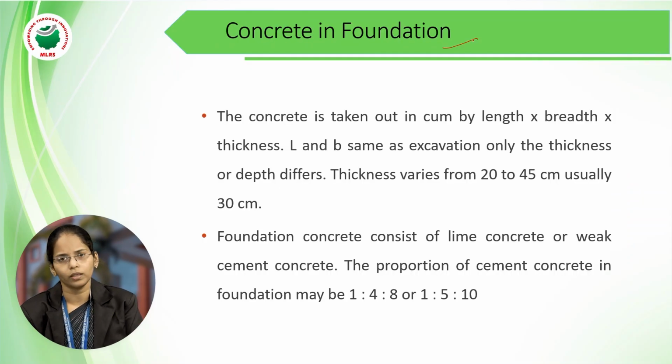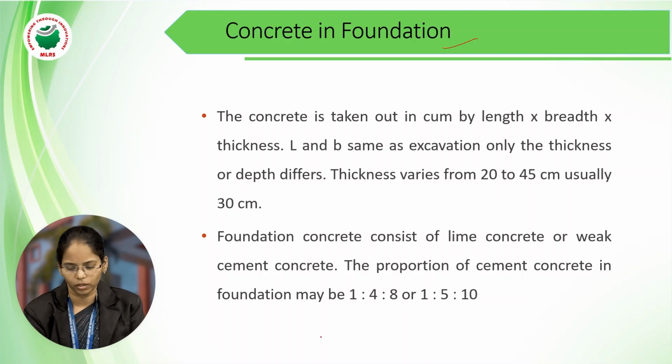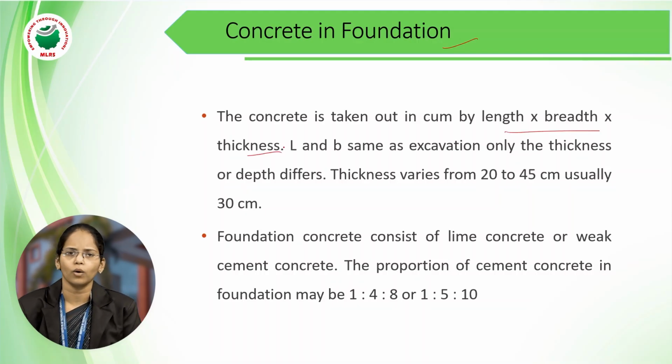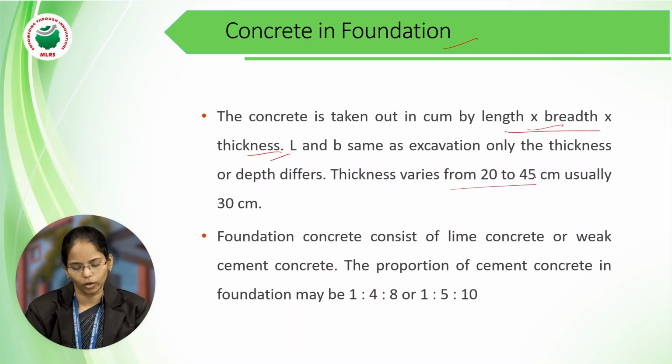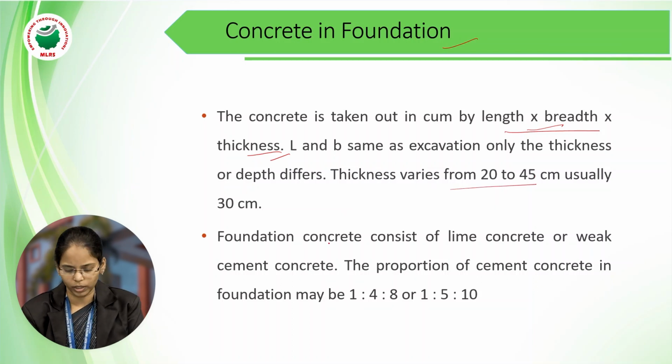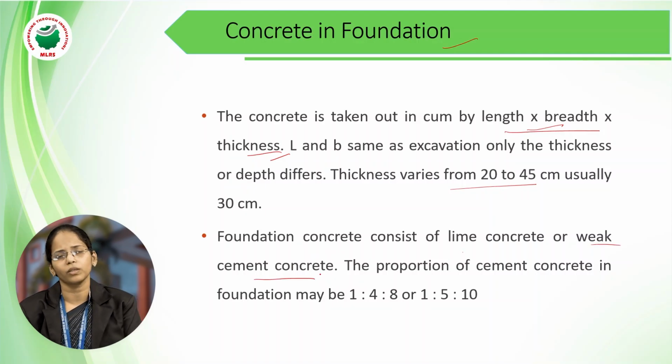Next, we need to lay concrete in foundation. Once the excavation is completed, we need to lay concrete in the foundation. The concrete is taken out in cubic meter. So again, as we dug the trench, L into B into H, same length into breadth into thickness. We require the concrete; the unit is cubic meter. The thickness varies from 20 to 45 centimeters, so it differs on the depth. And the foundation concrete is given by weak cement concrete. Weak cement concrete is nothing but Portland cement concrete.